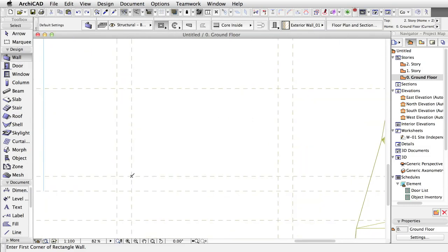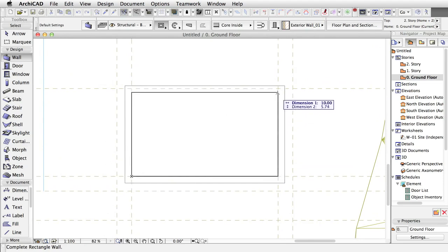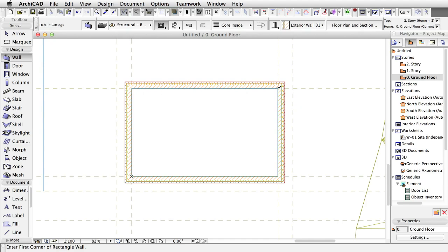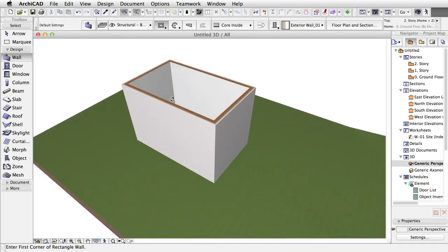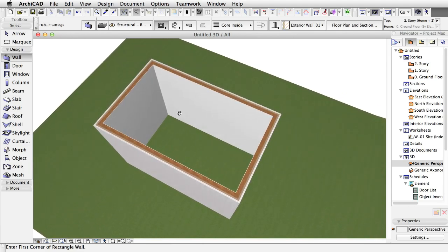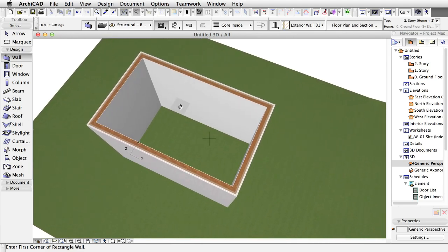When drawing the line of a wall, after the first click, a heavy black line follows the cursor like a rubber band. This line is the reference line for the wall, and the width of the wall is measured from this reference line. The reference line is used to connect walls smoothly and helps locate the walls with the cursor. Press the Ctrl and F5 keys to open the 3D window to see the result. Zoom in and use the Orbit command until you can see the interior.